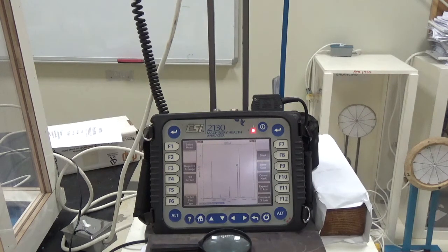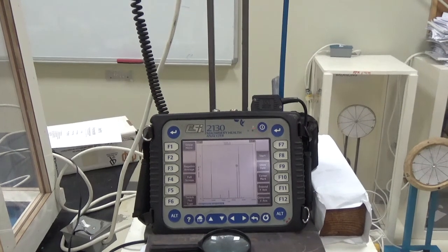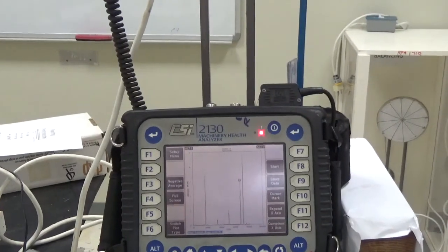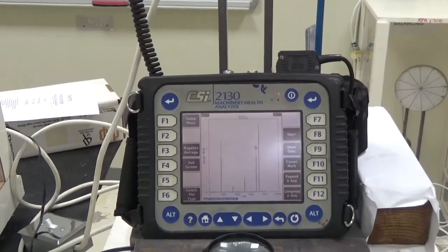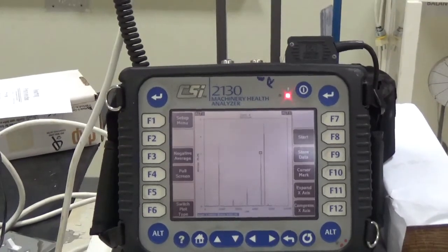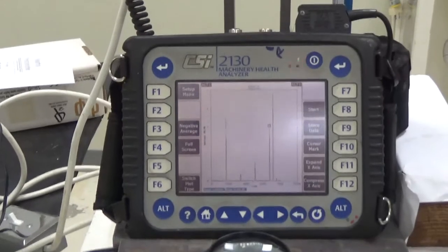And in the spectrum, when you see a frequency, you can find out that this is the frequency coming from a certain part. As you know all the frequencies which are generated from different parts, you can find out that so and so part is damaged or has got a fault, because the frequency you see in the spectrum is the same as you have calculated for that part. So this was about how to find frequencies and amplitude, and you can find them by spectrum. And now you understand what frequency tells you and what amplitude tells you.